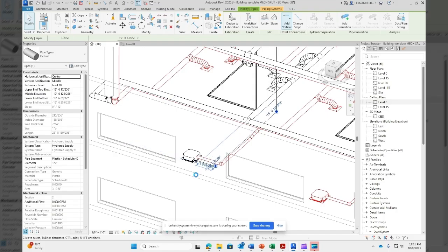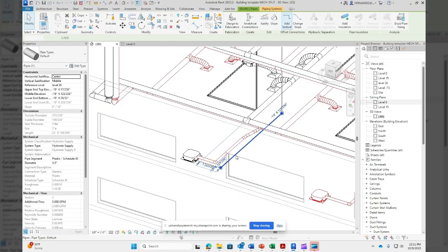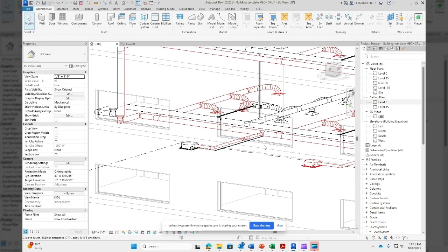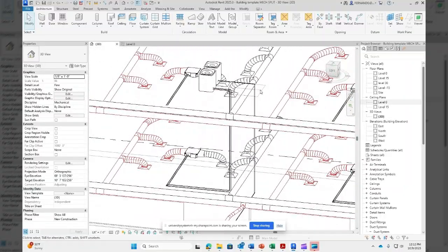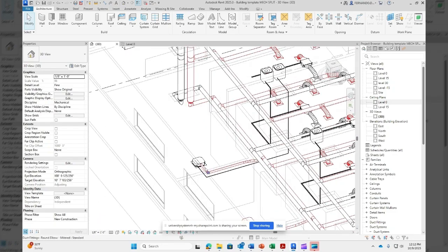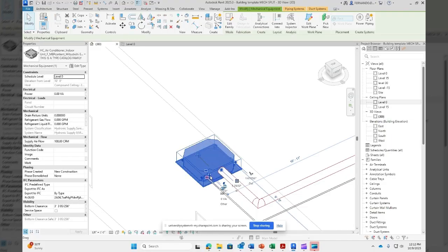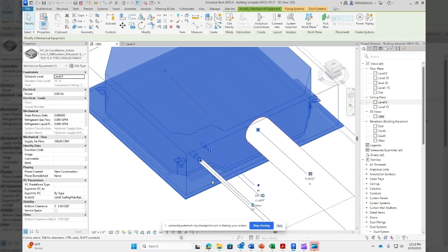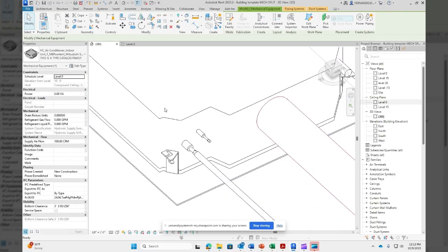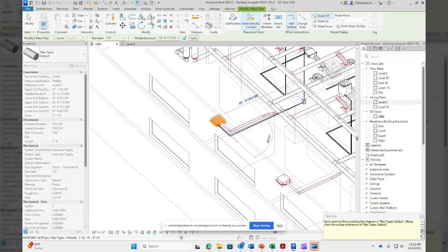But look at this, we have a beautiful conflict here. So what can we do? Probably we can move it in this direction, or we can move this one in the other direction until we fix that. Okay, and this is within the shaft. So it's getting more complicated. And finally, we have to connect. I think it's easier doing it by hand. So we are going to connect another, because we have two pipes here. So I'm going to connect. But once we have the first layout, the second is easier, because we know that we have to go parallel,